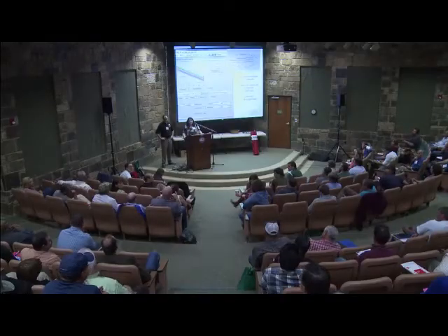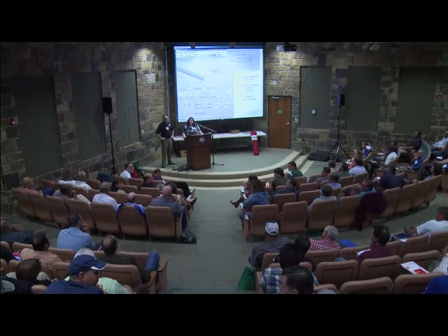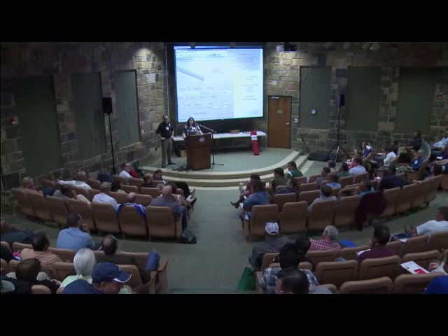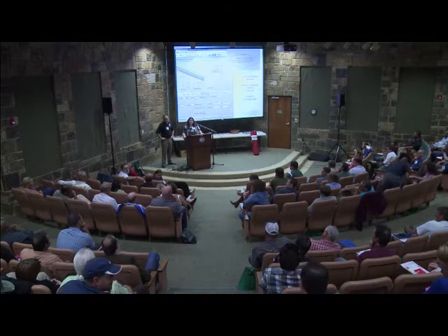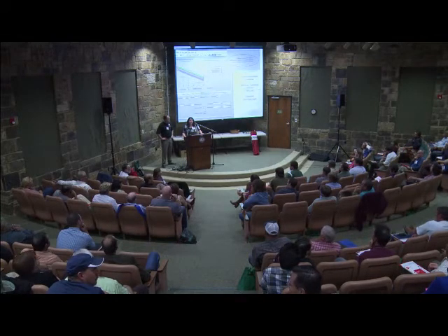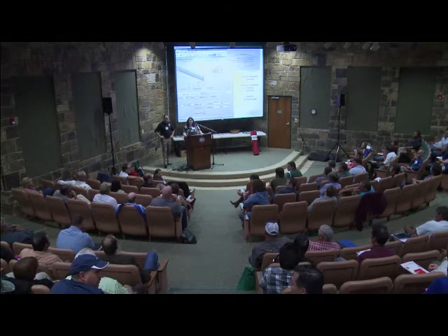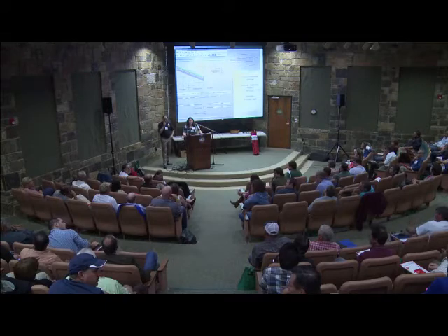The other thing I was going to ask is that I noticed earlier there was some discussion about sediment basins. My understanding is you're not going to allow just anybody to develop a sediment basin and submit it with a pollution prevention plan. That would require an engineer as well, wouldn't it? It depends. As Joe went through in his presentation, if you provide the 3,600 cubic feet... You're going to allow any layman to make that calculation on their own? We have. It's the design part of it for the 2-year, 24-hour storm event that is more on the side of practice of engineering. Thank you.